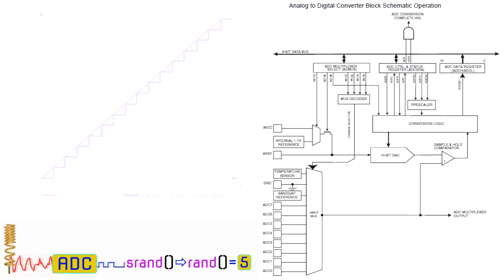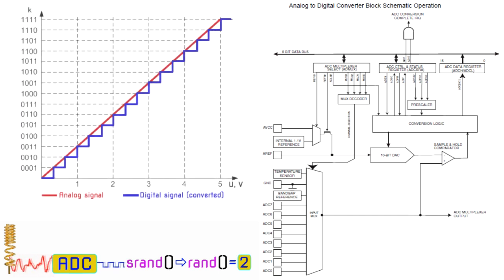For transferring external continuous information, analog information, into a digital computing system, we must convert it into integer, digital values. This type of conversion is carried out by an analog to digital converter. The process of converting an analog value into a digital value is known as analog to digital conversion. In short, analog signals are real-world signals around us like sound and light. Digital signals are analog equivalents in digital or numeric format, which are well understood by digital systems like microcontrollers.